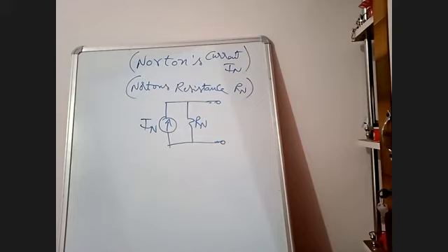In Thevenin's theorem, how have we converted? In series. Always resistance will be in series with the voltage source. But with a current source, always resistance will be in parallel. In source transformation also, we have stated the same thing. This point is very, very important.